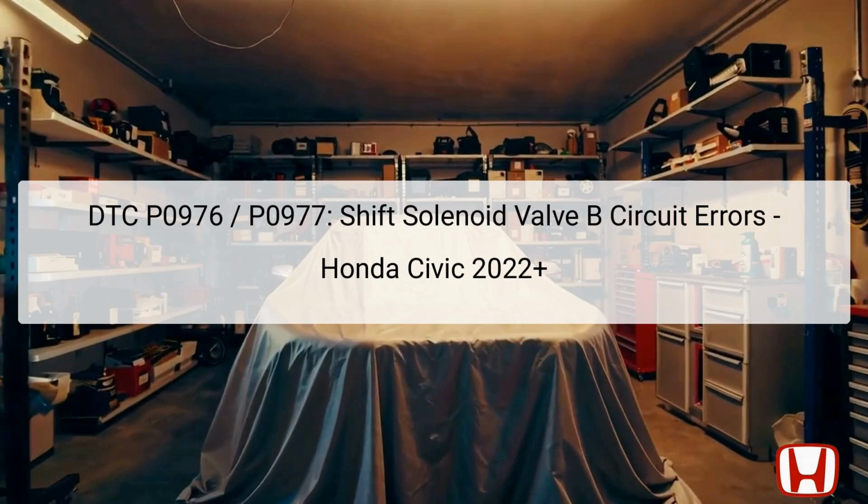This presentation addresses the diagnostic trouble codes, DTC P0976 and P0977, which pertain to issues with the Shift Solenoid Valve B in the Honda Civic 2022 and onwards. The DTC P0976 indicates a low circuit condition in the Shift Solenoid Valve B, while P0977 signifies a high circuit condition. The Transmission Control Module, TCM, is responsible for managing these signals and determining operational efficacy for gear shifting.